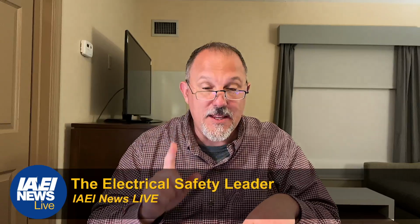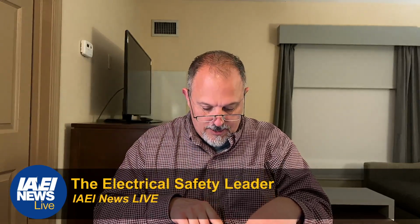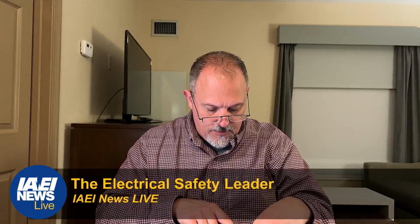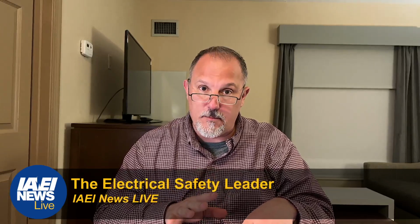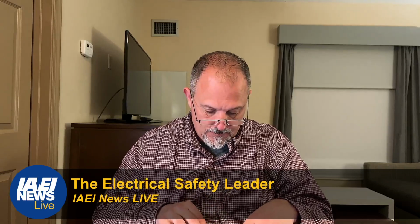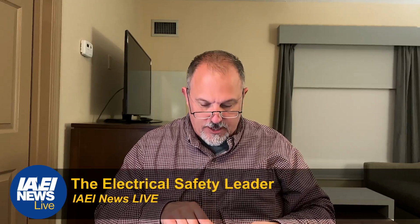It says in the parent text, for dwellings, all outdoor outlets other than those covered in 210.8(A). So this would not be the cord and plug connected. Exception number 1, excluding outlets installed in the following locations and supplied by single-phase branch circuits rated 150 volts or less to ground, 50 amps or less, shall be provided with GFCI protection.